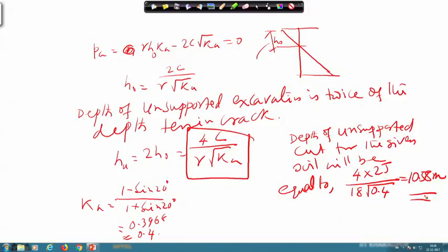When you excavate in sand, because of the absence of cohesion, when you cut a vertical cut, the sand will flow and make a particular slope, it will never be vertical. But if the soil has some cohesion, then you can make a vertical cut up to almost nearly 11 meter. So, this is the beauty in the strength property of the soil.